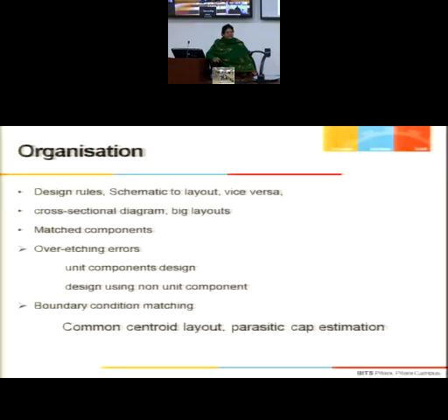So that if diffusion is going to happen, I will increase my mask length so that ultimately the channel length I will have, even after overlapping diffusion areas, I will still have the required value of the channel length. So I can take care of those things at the design stage.